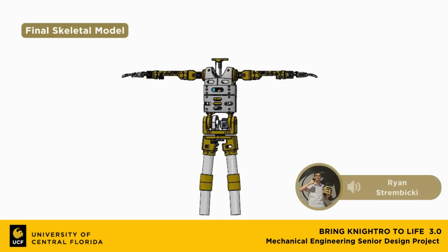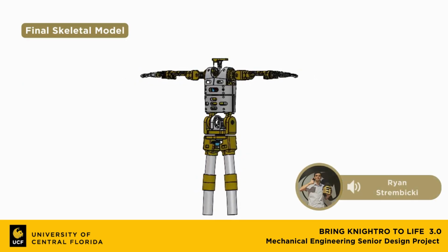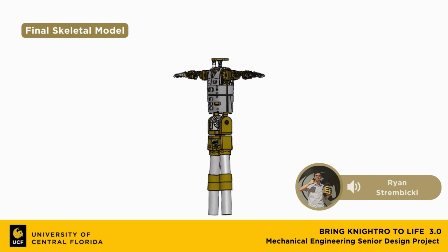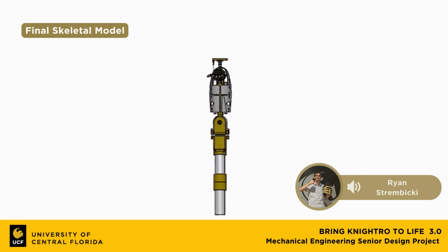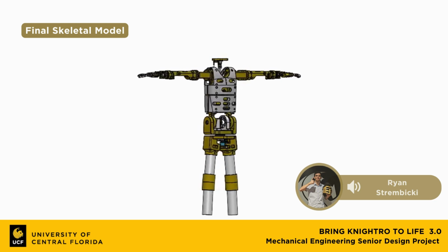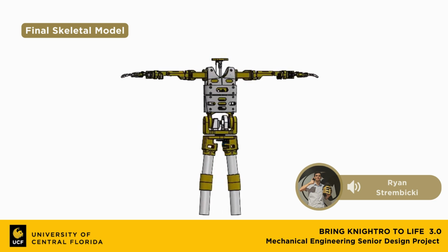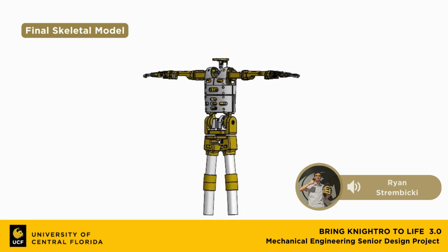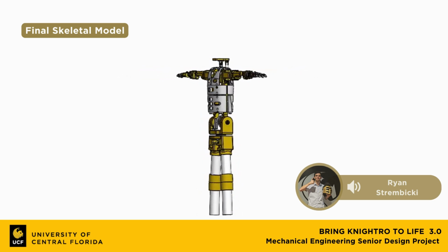For our final model, the scale of our figure was dictated by the size of our hand, which was the smallest mechanical assembly. The hand was designed using linear micro servomotors to actuate the linkage system for each finger. The hand was attached to a 2 degrees of freedom motion system utilizing a universal joint to pivot the system upon. A third motor then rotates the system via direct drive to complete the 3 degrees of freedom required for the wrist movement.